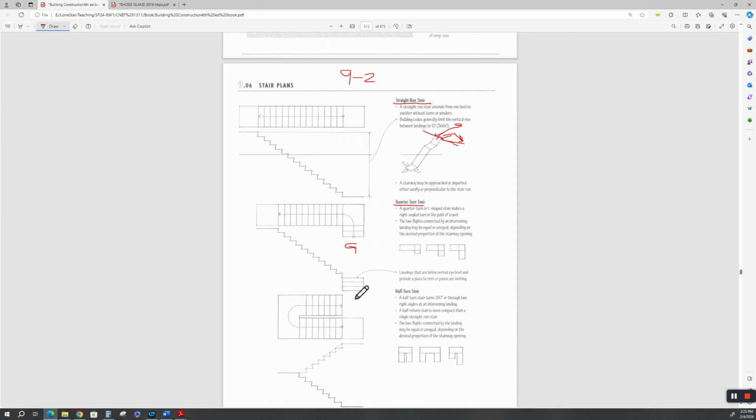So Bubba built my house, and these treads and risers are different. But it's okay, because once you negotiate this and you're getting on the landing, then you've got this flat piece of real estate up here. You turn, and then you start an even riser and tread pattern all the way up. We talked about before about changing the riser and tread pattern up through here. That's a disaster waiting to happen. You do that, you're probably going to get red tagged when the building inspector sees it. And you really don't want to get red tagged. So that means you got to tear all this out.